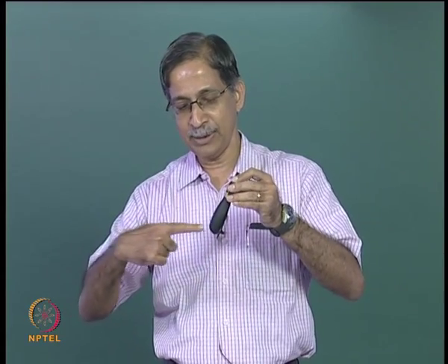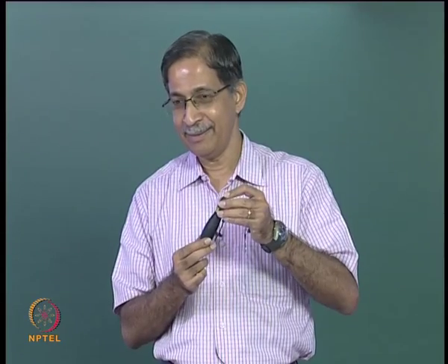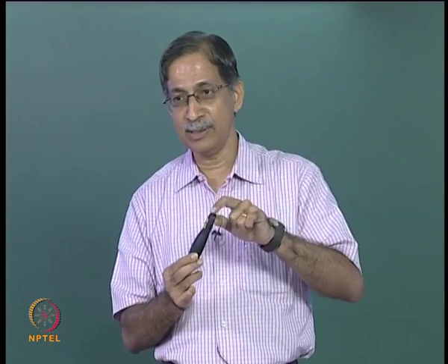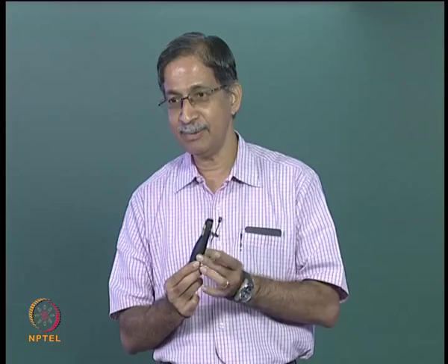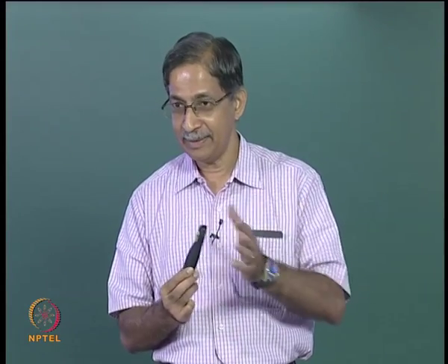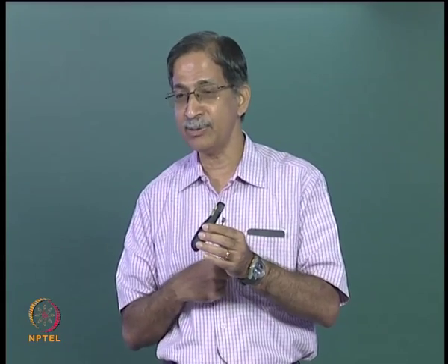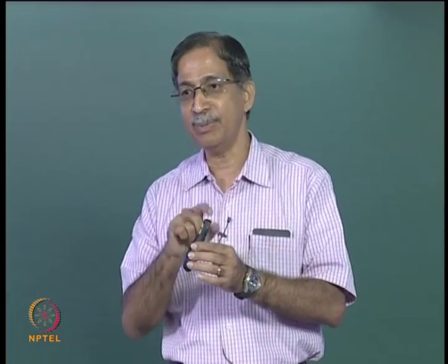So whether I push it this way or this way, I am going to get minus, but whether I pull it this way or this way, I will get this member elongating, plus. Does it make sense now? At the start node, for the directions, we assume you will get minus minus plus plus.